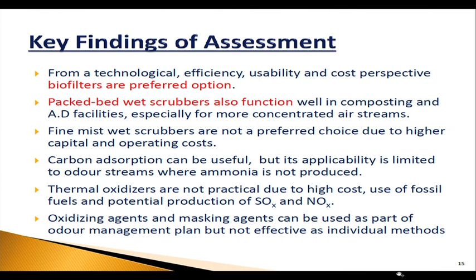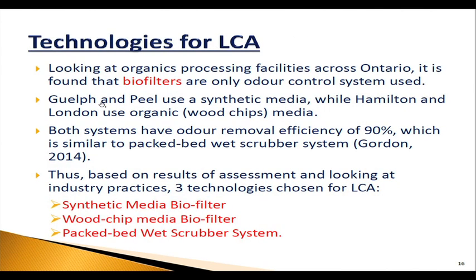Oxidizing agents and masking agents can be used as a part of a solution, but they are not effective as individual methods. So, you can have a combination with others. Based on this, we looked at the packed bed wet scrubber and the biofilter. Those two we chose to go for LCA. In terms of biofilter, we had two types: a synthetic media biofilter and a wood chip media biofilter, and then we had the packed bed wet scrubber system. So, we took these three technologies.